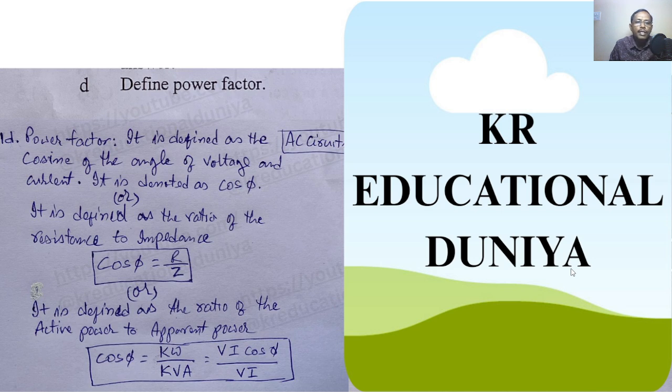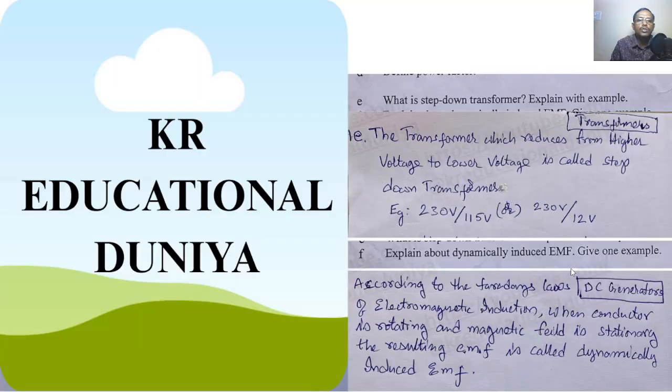That is one definition. Another definition is that it is the ratio of the resistance to the impedance, cos phi equals R by Z. One more definition is that it is the ratio of the active power to the apparent power, that is cos phi equals active power by apparent power. Active power formula is VI cos phi, apparent power formula is VI. So VI gets cancelled, and cos phi remains. The unit for active power is kW, the unit for apparent power is kVA. Like that you can write. Next question.